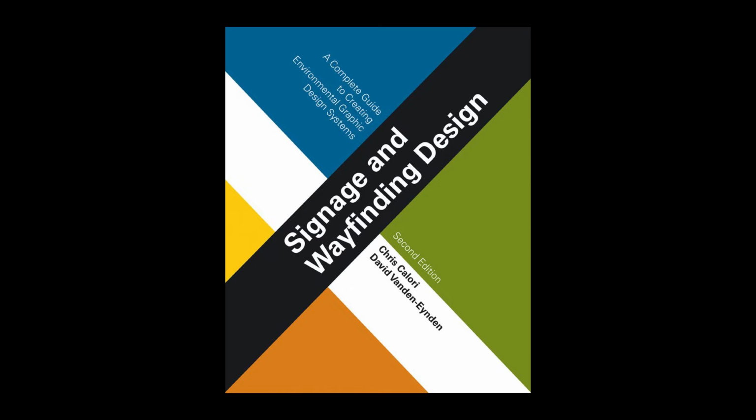Some internally illuminated signs aren't even rectangular boxes. Instead, they're individually fabricated letters that can be lit in 3 ways: with light coming through the face of each letter, with light coming through the face and returns, or sides, of each letter, or with light spilling out around the returns of an opaque letter in a halo or silhouette effect.